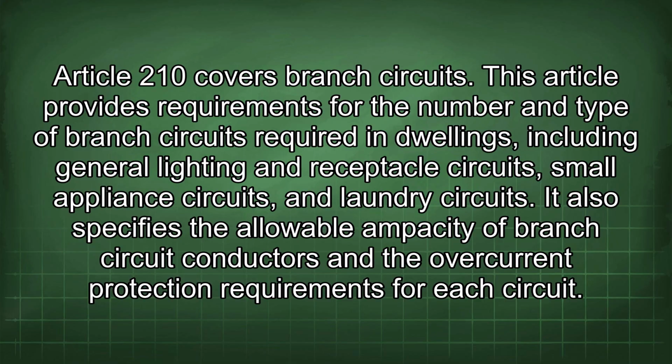This article provides requirements for the number and type of branch circuits required in dwellings, including general lighting and receptacle circuits, small appliance circuits, and laundry circuits. It also specifies the allowable ampacity of branch circuit conductors and the overcurrent protection requirements for each circuit.